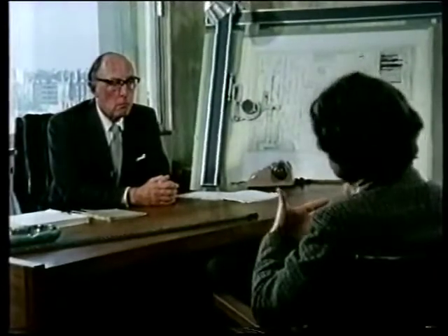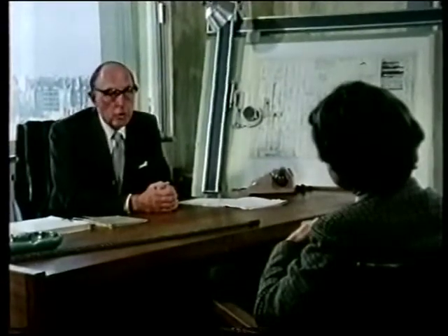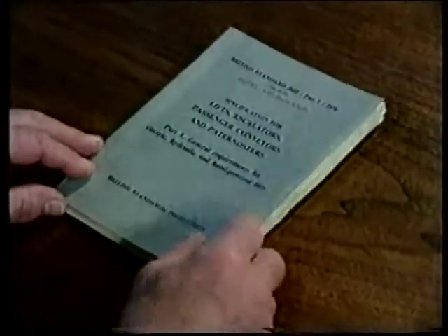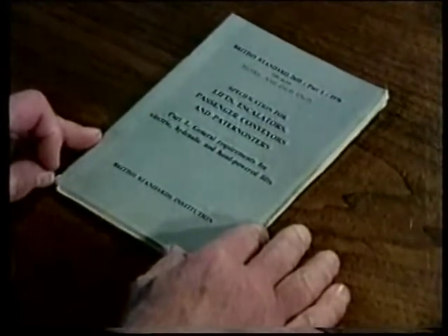So with the lift motion and the loading established, you're then able to go ahead and choose a machine to do the job. Yes, in this case we decided to use a perfectly standard, if large, machine used in the lift industry, and to employ this in a coal mining environment, but also to incorporate all of the safety devices we would normally incorporate on a lift installation. Now, these safety devices are spelled out in considerable detail in British Standard 2655, General Requirements for Electric Lifts.